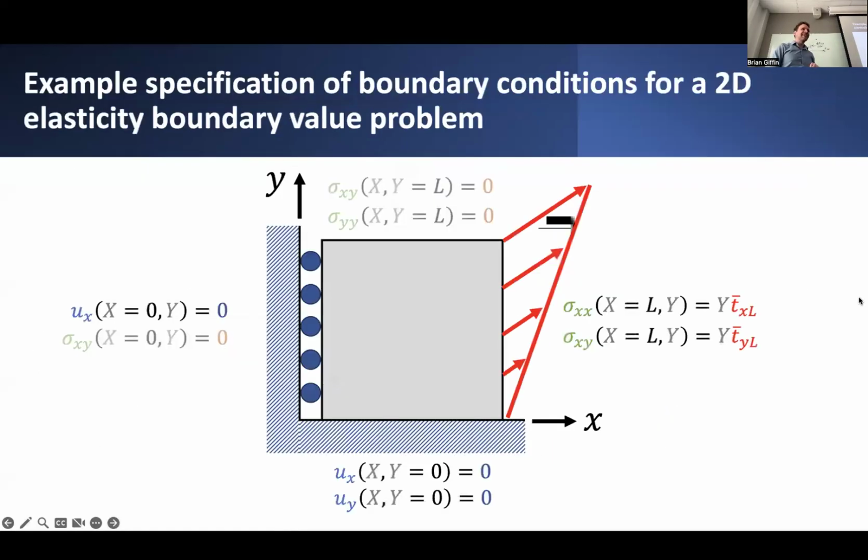And to give you a particular example, let's suppose you had this particular cube of material. And let's not do cubes. Let's actually make it even simpler. Let's suppose it's just a two-dimensional block. And in this case, I can define boundary conditions on each of these different four faces of this two-dimensional block. Let's say on the bottom face, I'll fully constrain displacement in both the x and y directions. That's kind of like a fully fixed boundary condition, where the full vector of displacements is just fixed. You're disallowing transverse displacement and normal displacement relative to that bottom surface.